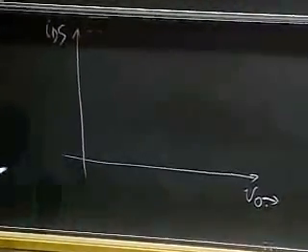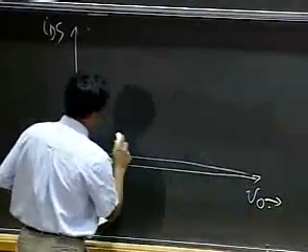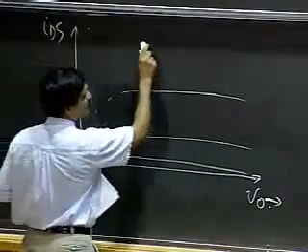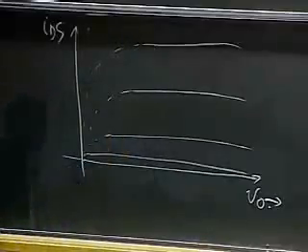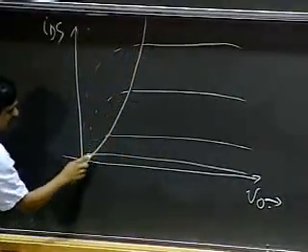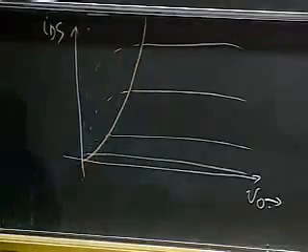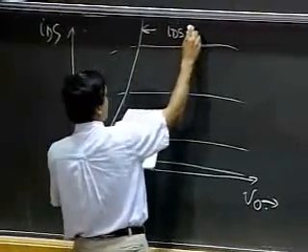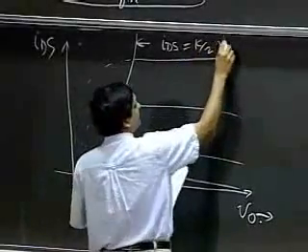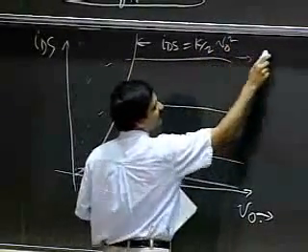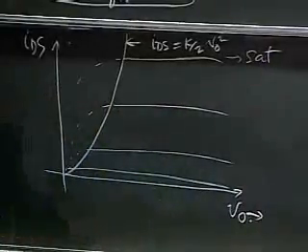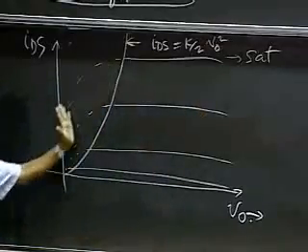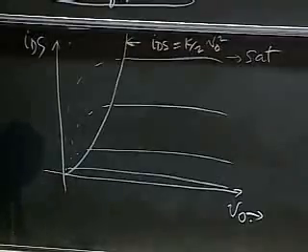And I said we draw that by first plotting the MOSFET curves, and we know that at some point the MOSFET gets into saturation. So this curve was IDS equals K by 2 V naught squared, and to the right side of the curve, the MOSFET is in saturation, and we said we're going to adhere to the saturation discipline and operate in this regime. Okay, when the MOSFET gets into this region, it is in its triode region.